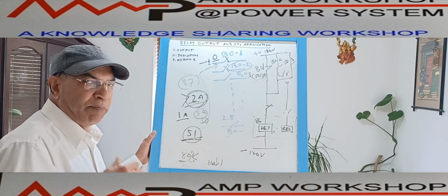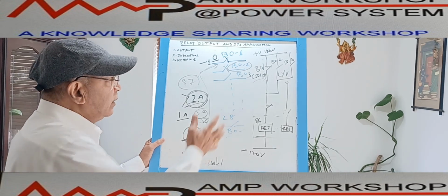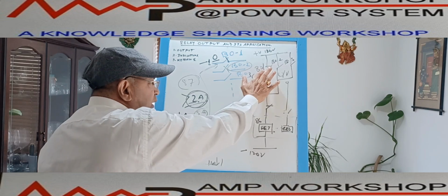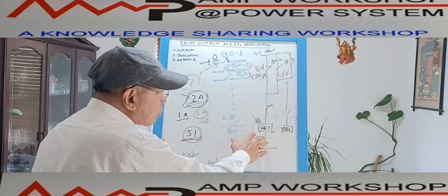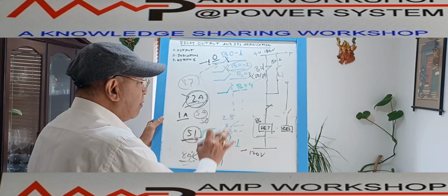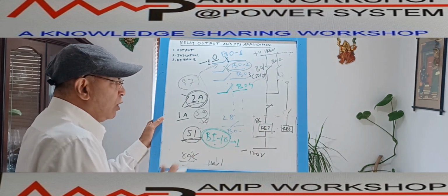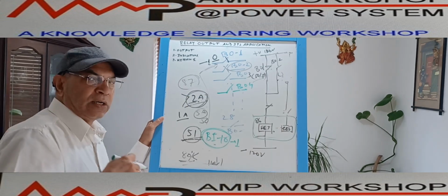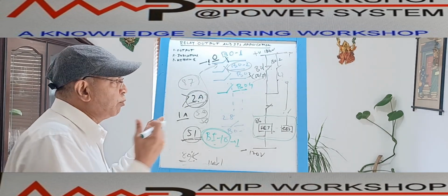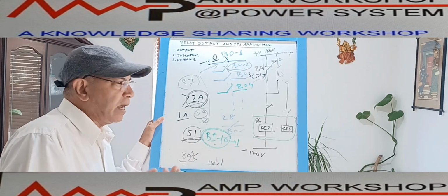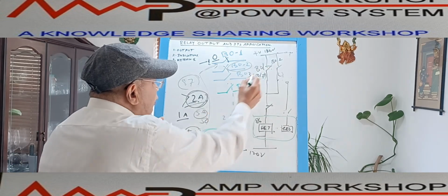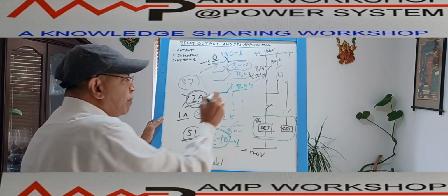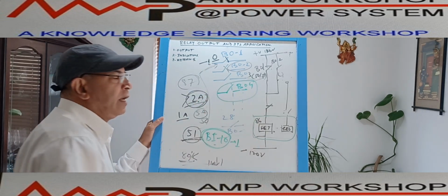Now we have shown in the previous tripping circuit that this lockout relay is manually reset through the push button. But if I want to make an auto reset, suppose these are the protection functions activating the relay. When this protection function comes back to normal, I want this relay to be automatically reset. Now if we want to auto reset, what do I have to do? When this corresponding protection function has come back to normal, or this protection, due to the fault being cleared from the line, then the corresponding function, the B01 or B02, will come back to normal. So if B01 comes back to normal, at that time we can configure B04 as activation.